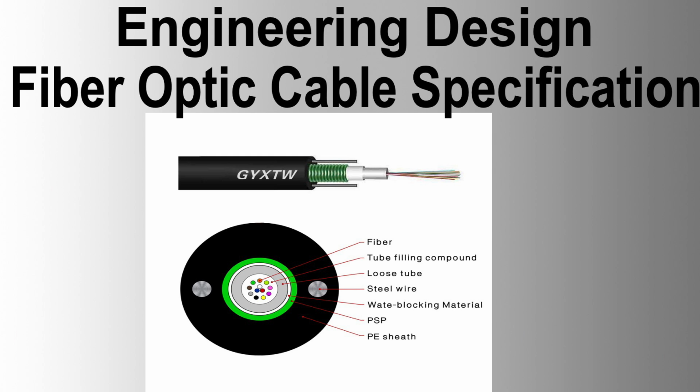Fiber optic cable installation test. General. All cable types shall have been subjected to type tests according to relevant standards. A drum test shall be carried out prior to unrolling to ensure the cable has arrived undamaged. Installation tests shall verify cable quality before splicing. After each splice, tests shall confirm workmanship quality before sealing the splice enclosure. After all splices are complete, overall end-to-end parameters shall be measured.